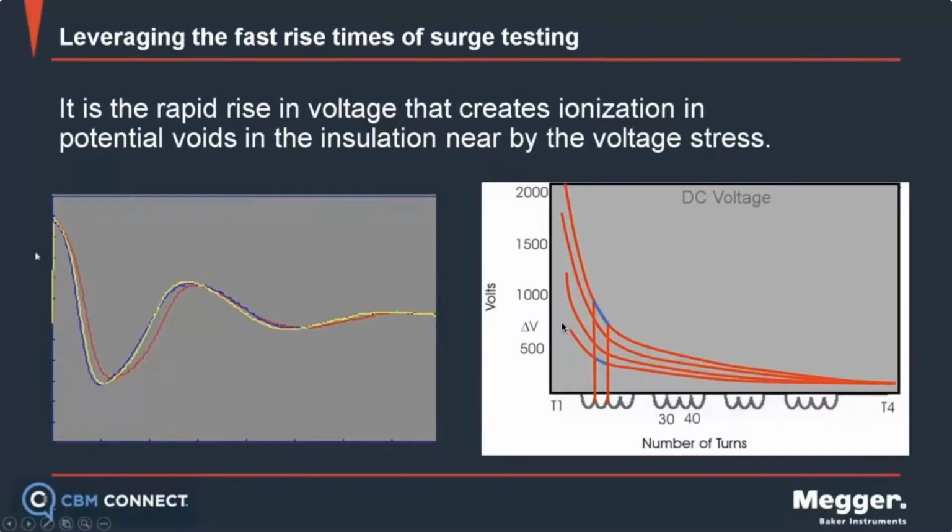The high frequency discharges, if they were displayed on here, the voltage is so small, typically in the millivolts with our resistive divider network, we wouldn't see it normally riding on the surge pulse. If the partial discharge is very large in amplitude, it is possible to see maybe some riders there. But we use special filters and processing equipment to isolate those high frequency regions of the waveform.